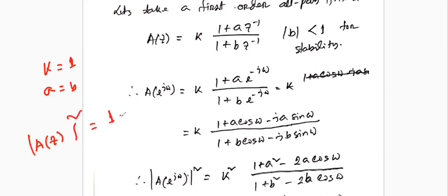We are happy with that. Whenever we took the value A(z), that is the transfer function of the all-pass filter, we found that this is equal to 1 and this is, again, equal to 1. So altogether it gives 1, and there is no imaginary part. The imaginary part is equal to j0. That means it has the magnitude 1, but there is no non-linearity of the phase. So you don't have the phase quantity here. You can't control your phase. You can have only the magnitude 1 for all the frequencies.